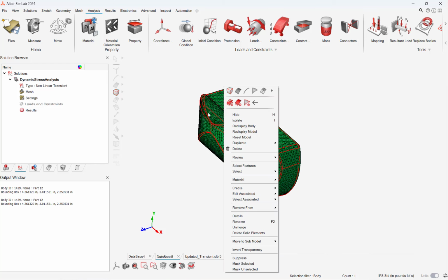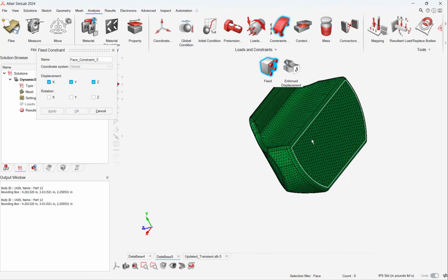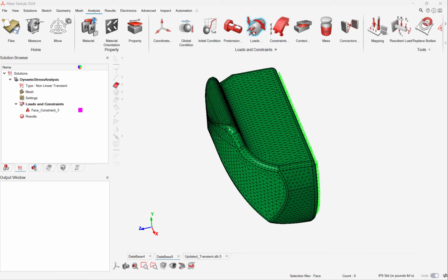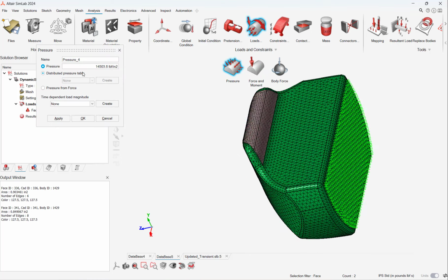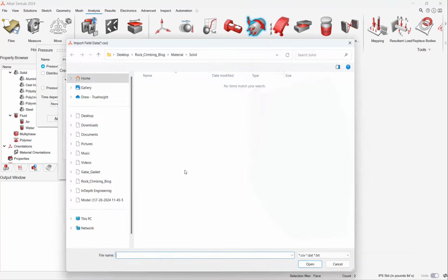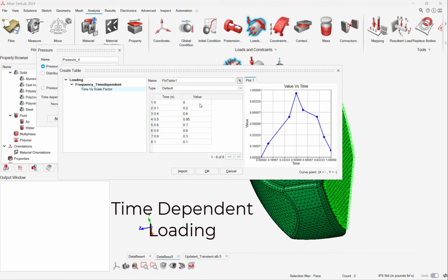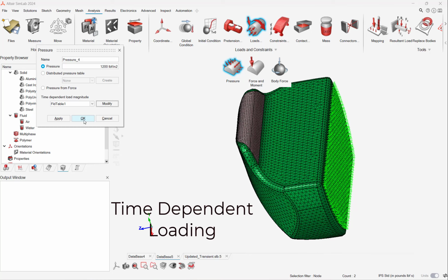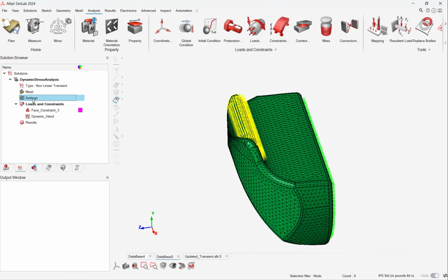After assigning the material properties, I can now apply the restraints and loading. I will fix the planar face in all directions to represent the hold on the climbing wall. I then apply the force in our model. I will apply a time-driven load, as this load could represent a climber jumping and grabbing the hold. In our case, the load that I key in is 1,200 pounds, but with the scale factor, the load could increase or decrease across the time of the simulation.